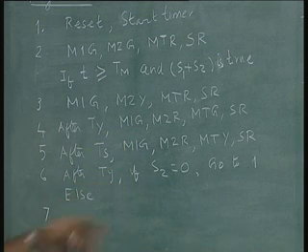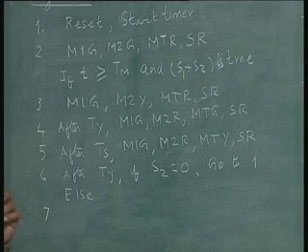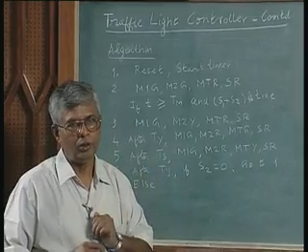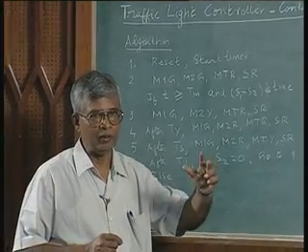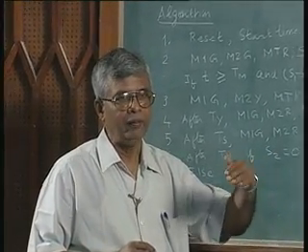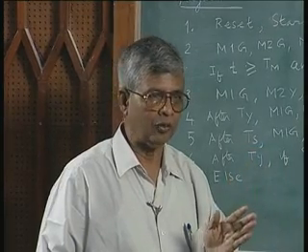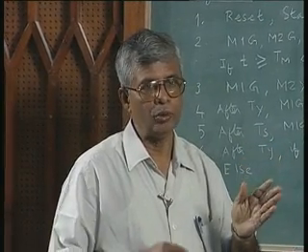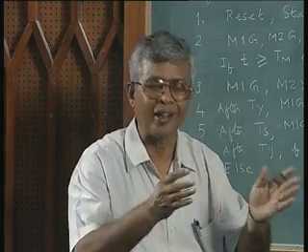side to the main. So, in this case what we have specifically assumed is that the main road from left to right will be green when you allow the turning from the main road into the side road, whereas the same green from the main road from left to right will not be green when you allow the turn from the side road to the main road. That means the traffic in the main road should be stopped in both directions now.